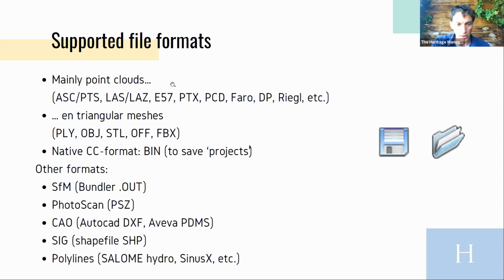And most of the times we will be working with LAS data. So this is standard data for laser scanning point clouds, especially when you work with airborne laser scan data. These are most of the time delivered in the LAS format or in the compressed LAZ format. This is a binary-based format, but very well documented by the American Society for Remote Sensing.